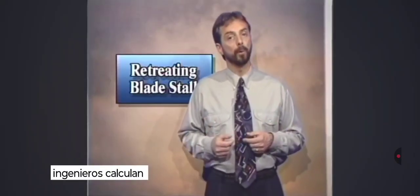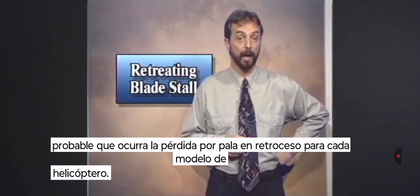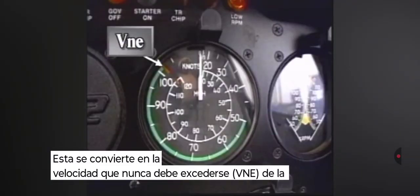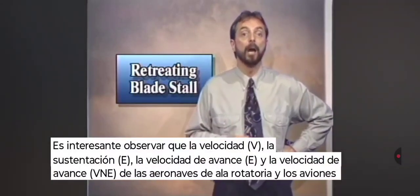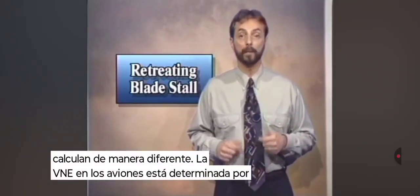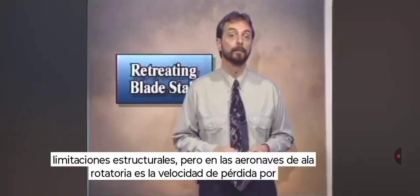Engineers calculate the forward airspeed at which retreating blade stall is likely to occur for each model of helicopter. This becomes the rotorcraft's never exceed speed, or VNE. It's interesting to note that VNE in rotorcraft and VNE in airplanes are calculated differently. VNE in airplanes is determined by structural limitations, but in rotorcraft it's retreating blade stall.